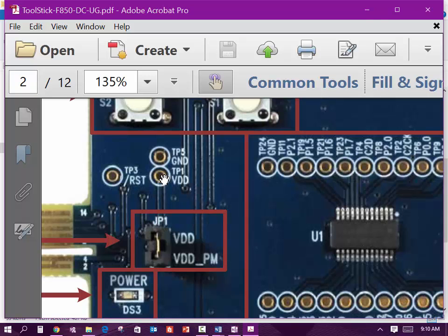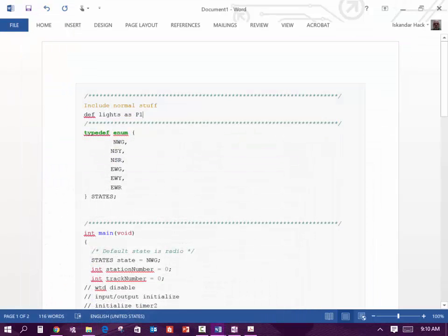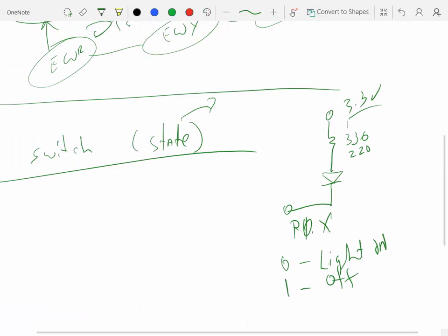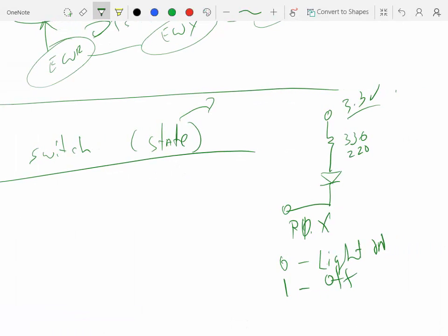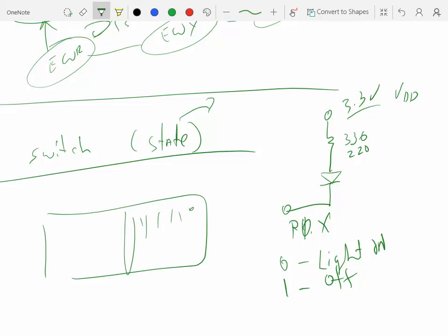So when you go back to this drawing here, this goes to the VDD on the board right there. And you can just put that along the top of your board right here. Just bring your 3.3 volts out, and then bring your 6 resistors over here. Remember that there's a jump of space in the middle of the board, so right there. And you don't have to hook up the ground up there. So then you would bring your other 6 connectors off here.